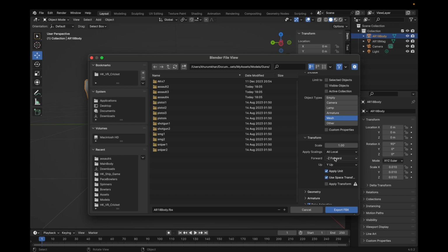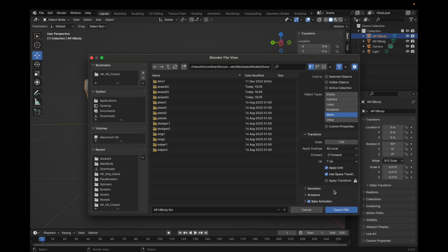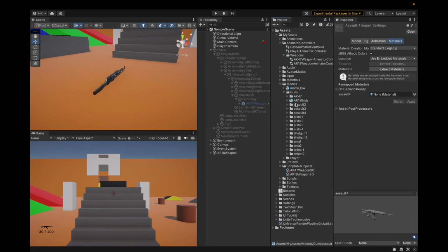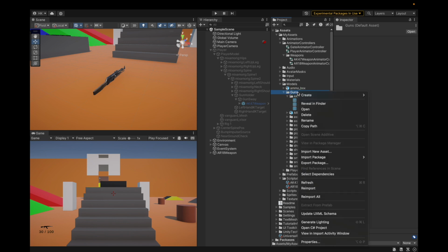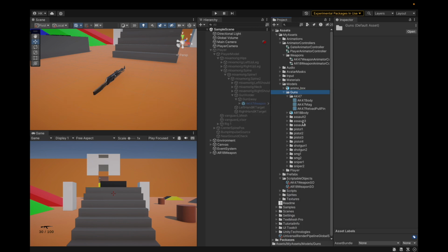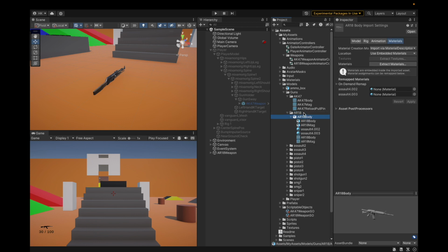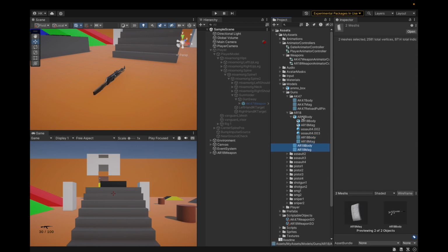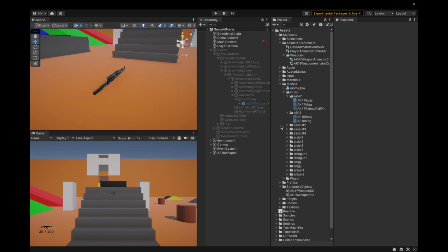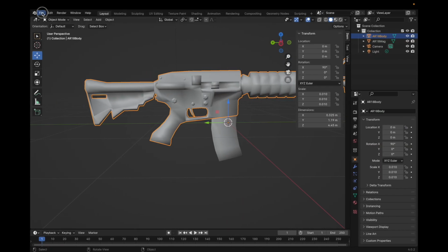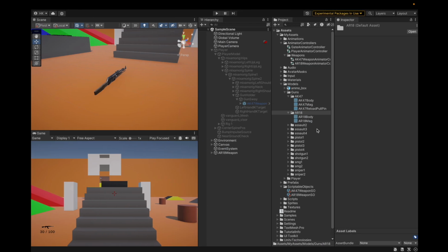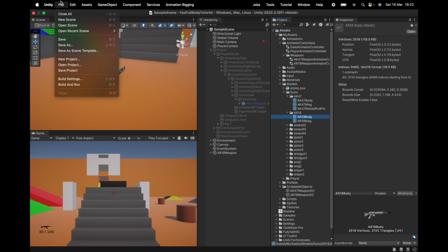Once we export, just only mesh, I don't want anything else. You can see I've changed settings, so my forward axis and everything else must be like this, and you'll have everything correctly done. So export, sorry, and we have this nice little body. Create a new folder, and you can say AR18, pasting in this one as the very first FBX file. You may have noticed it's already imported both for us. I'm not sure why, because I did not select selected objects only. Actually, I forgot to check this, but that's okay. So we've got the two files that we wanted even without doing that.